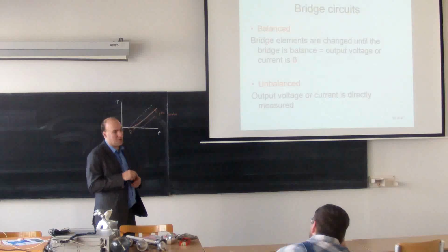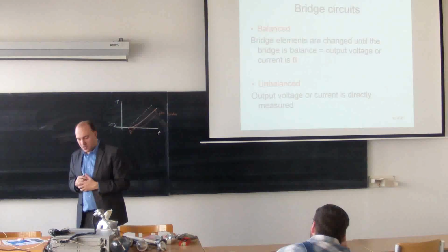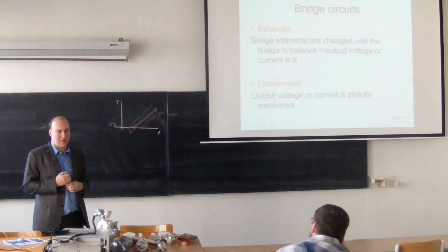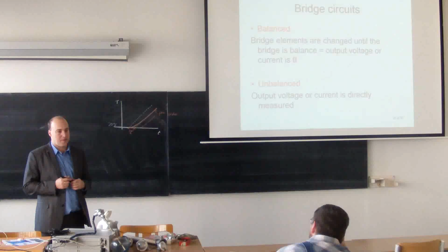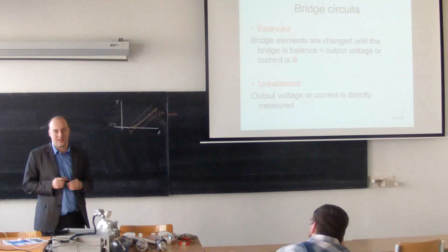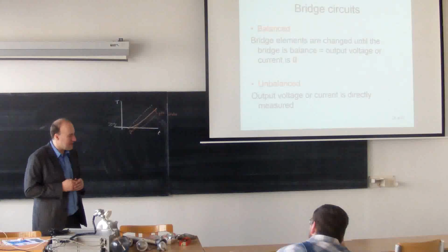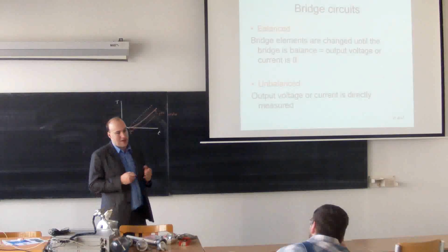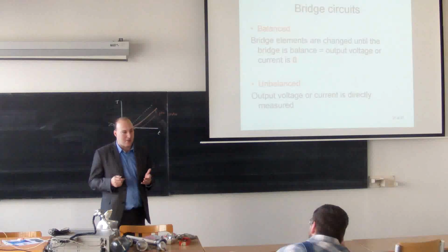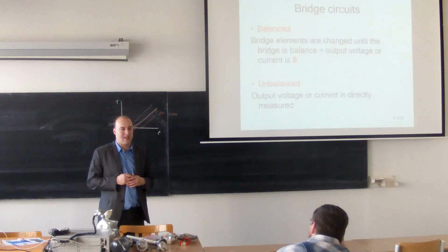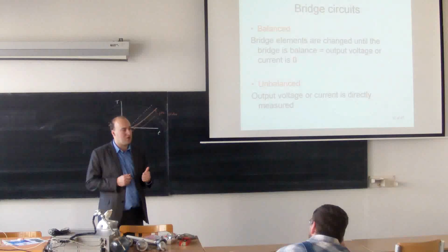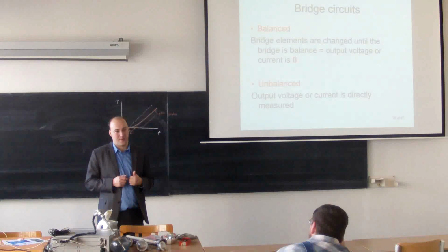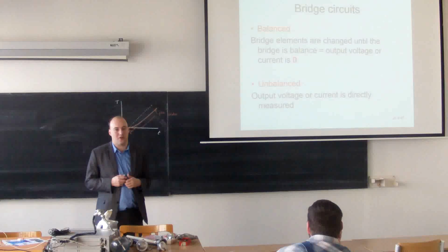This will be called a balance bridge. This obviously takes some time before I will be able to balance the bridge. So balance bridges are used in labs where you don't really care about how long it will take. But the big advantage of this balance bridge is that you don't need to care about linearity. Zero is zero. I don't care if it's linear or non-linear.